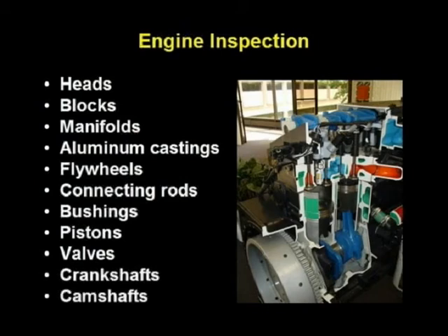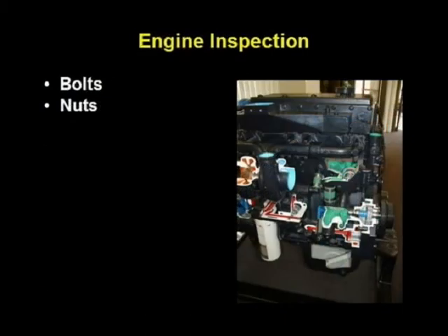Crankshafts and camshafts have been inspected by magnetic Barkhausen noise for residual stress problems due to grinder burn, and by ultrasound for cracks. There is an ultrasonic method to measure the case depth on crankshafts after heat treatment. Many bolts, nuts, and other heat-treated components have been checked for hardness or case depth using eddy current methods. Eddy current methods were used to check the select injectors for proper ion nitriding. Eddy current methods have been used to inspect wire prior to forming into springs. Magnetic particle inspection is performed on formed springs.